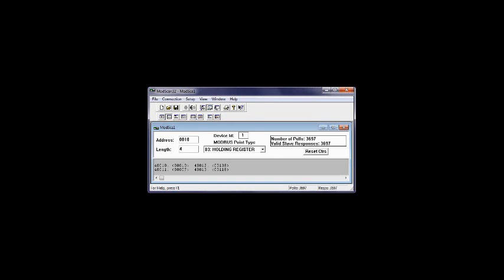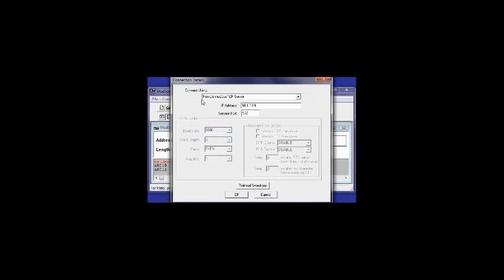I've actually got this one running here already. I had it running and forgot to disconnect, so let me reconnect and show you what it looks like. I'm going to go ahead and do a connection, and I'm going to connect to this remote Modbus device. You just saw in the previous settings that I have an IP address assigned for this, and that's all you need to do from your Ethernet side: say go to the Modbus device, here's the IP address of the device I want to go to, and then let's go ahead and connect.